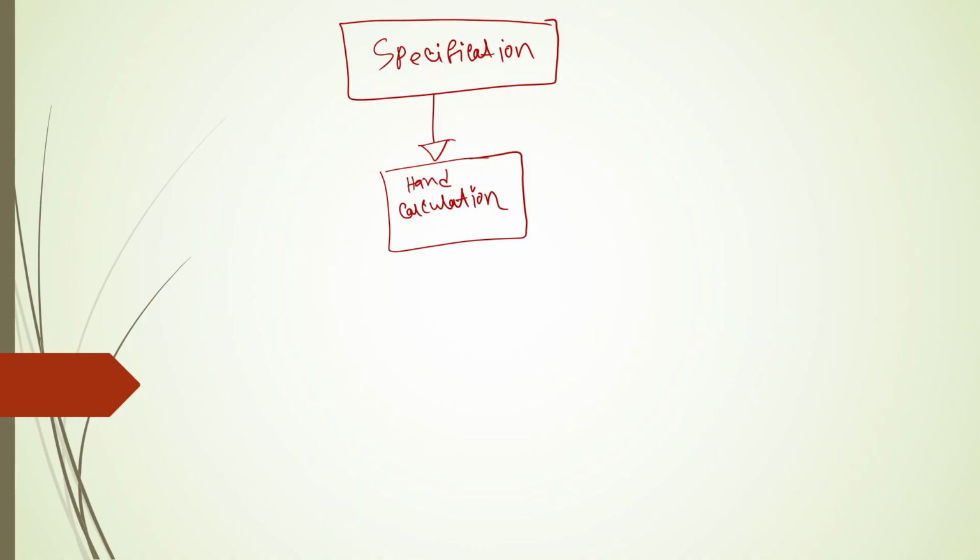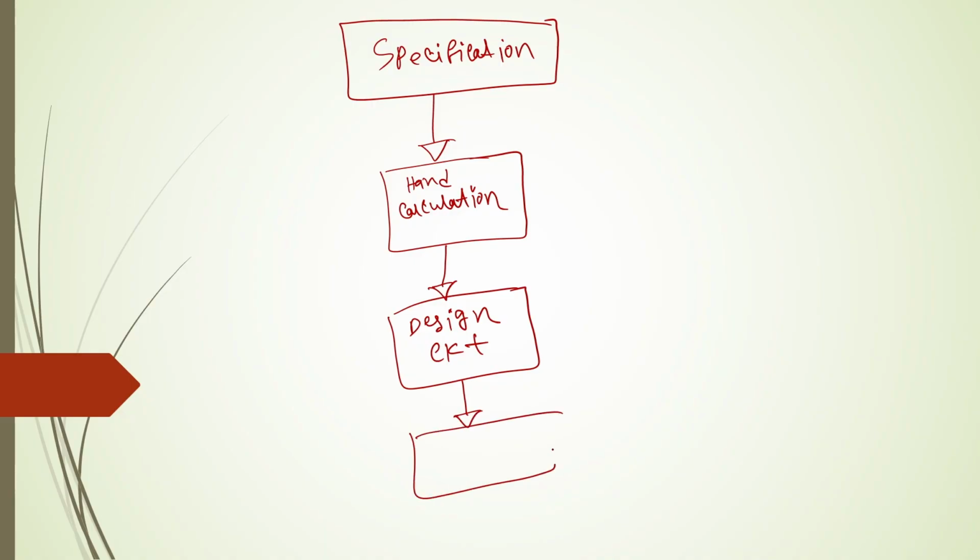Whenever the hand calculation is done, we design our circuit using the calculated values, and after that we draw the schematic in some simulation tool, like Cadence.